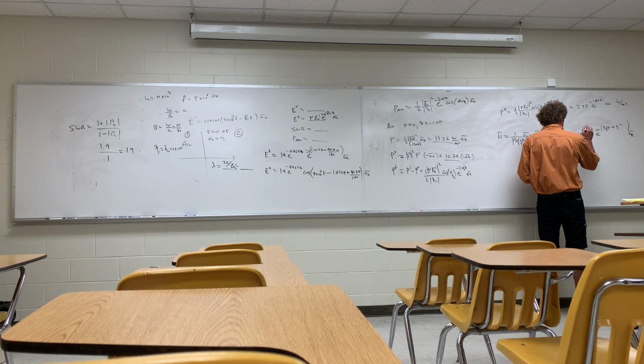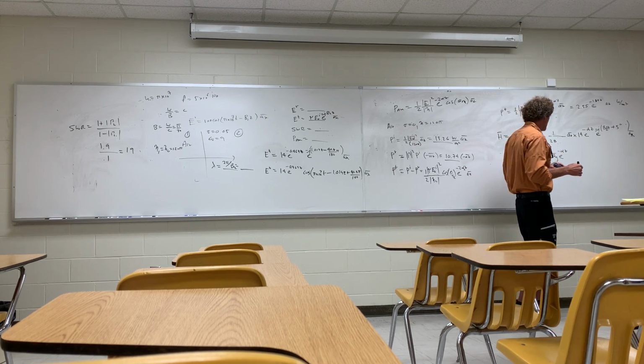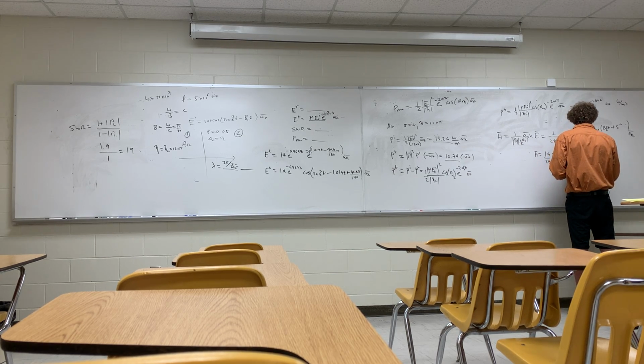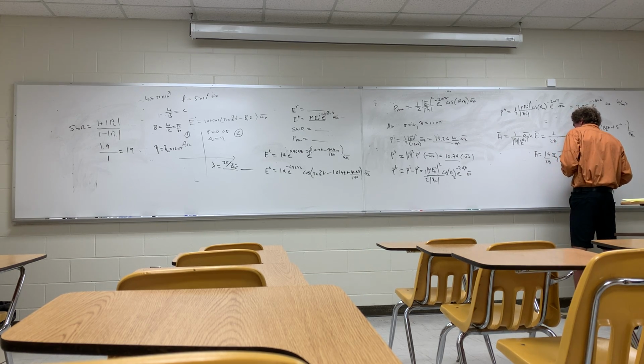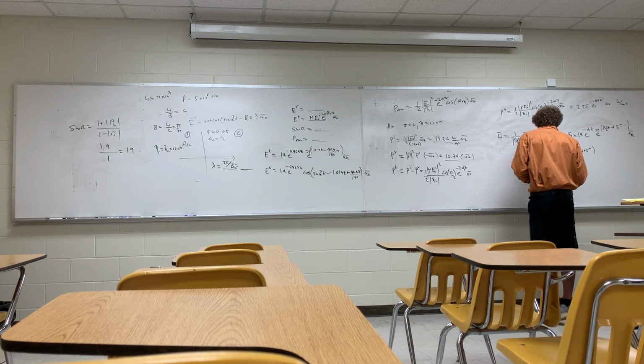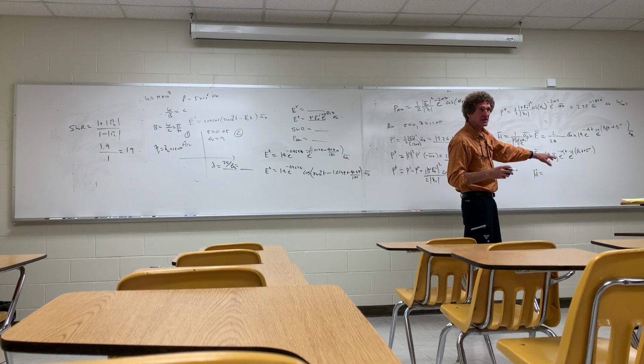Order doesn't matter here. It's e to the minus alpha z. Alpha is about 0.92 or something like that. Then I have e to the minus j beta 2, I'm just going to leave this beta 2 here, times z plus 5 degrees. And now I want to take it into the time domain. So this is phasor. Do y'all agree with what I put up there? How do you get it into the time domain?